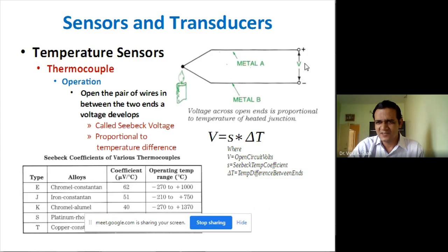And it will generate a millivolt signal as an output of this. This millivolt signal we can further amplify and we can utilize that for voltage measurement purposes. And using that voltage, we can convert back into the degree Celsius temperature. So we have to set a relationship between this voltage, which is generated here in terms of millivolt initially, which is amplified further, and then it should be converted back into our degree Celsius temperature.